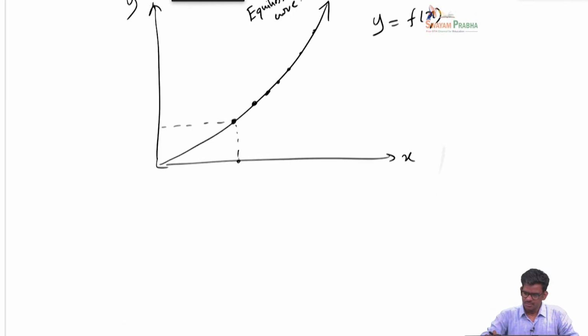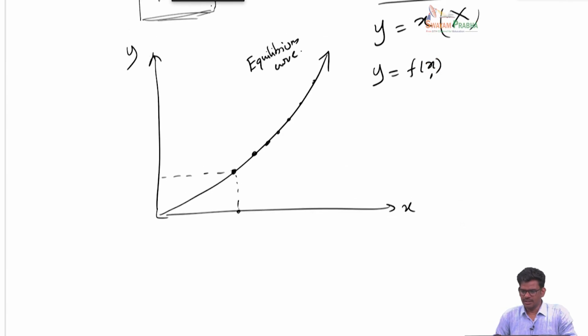Now, when you look at this equilibrium curve, it is not telling everything about the equilibrium nature of this entire system, because the system contains air and water also. This functional relationship is only for ammonia, the solute of interest for us. So, this relationship is only for ammonia's composition in the gas phase and in the liquid phase.